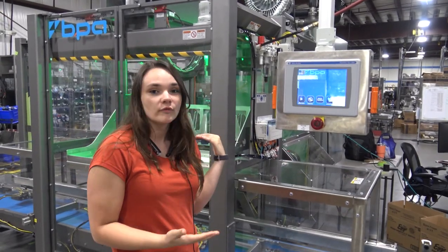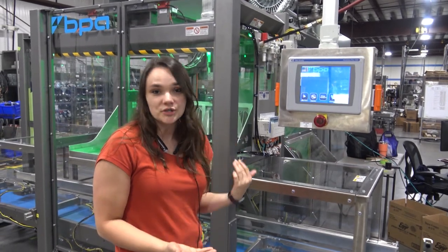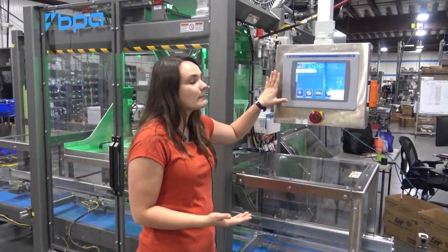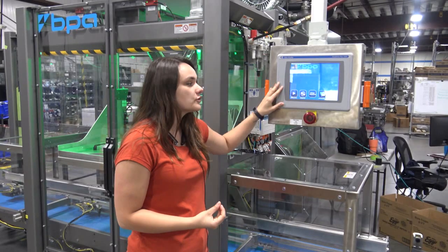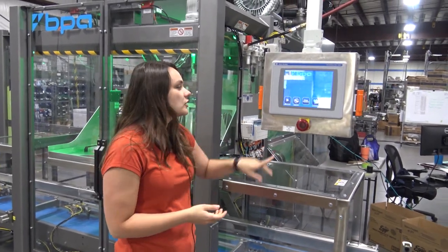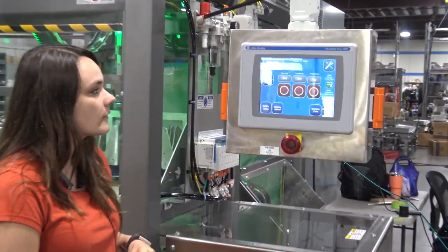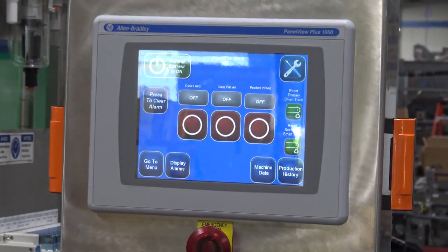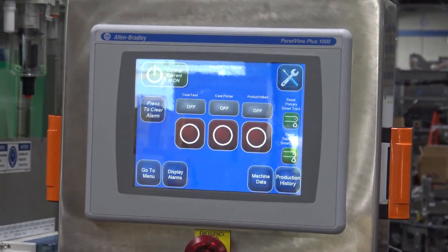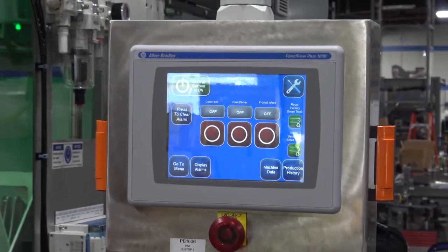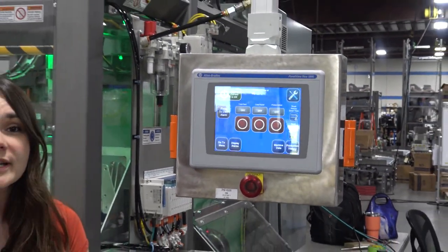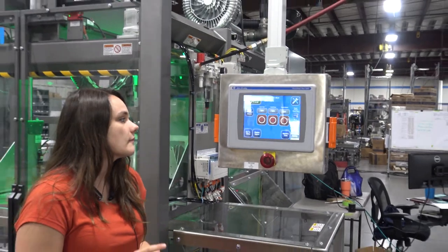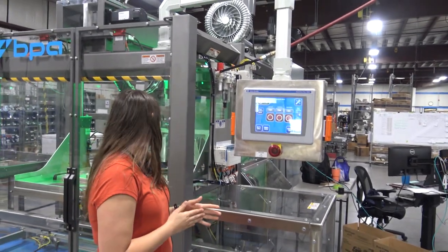I'm going to give you an overview of how the machine operates with the HMI. So this is our main menu screen. To get to the start buttons of the machine, you hit System Control. You will then turn Control Current on for the machine. Make sure all the robots will home. The Smart Track belts will reset after every e-stop. Okay, so that's to finish.